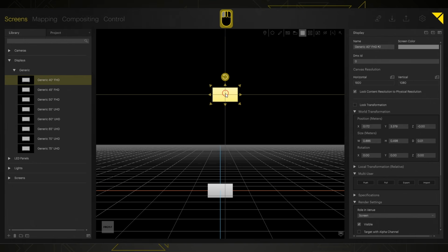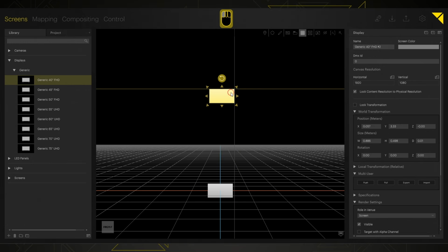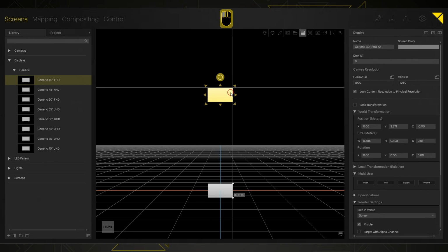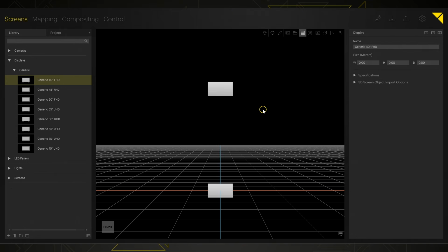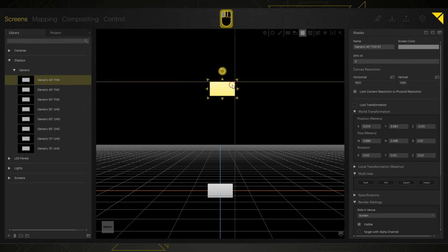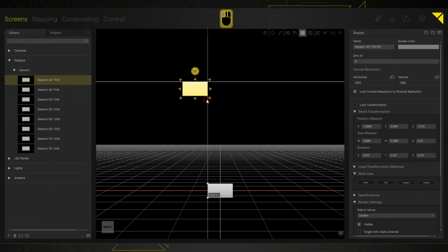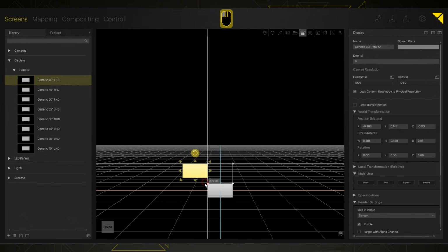So if I click in the middle, it's that center point, or in the top right, it becomes the top right corner of my object. And if I press shift once, I'm not going to hold it. I just press it one time. That gets me a horizontal shift. And if I press shift again, that gets me a vertical shift. So if, for example, I wanted to snap this corner to this corner, I would grab this object in the top right and then press shift one time so that I could align it with that corner, and then press shift again to vertically align it down here.